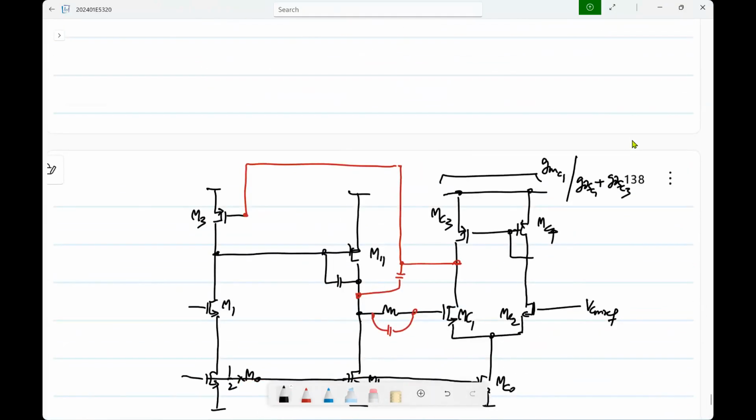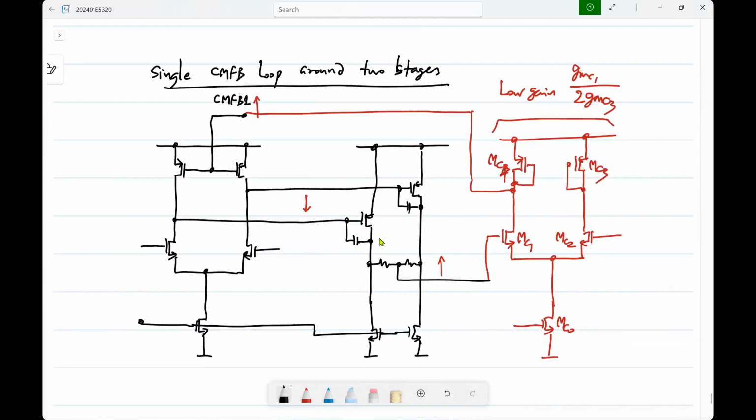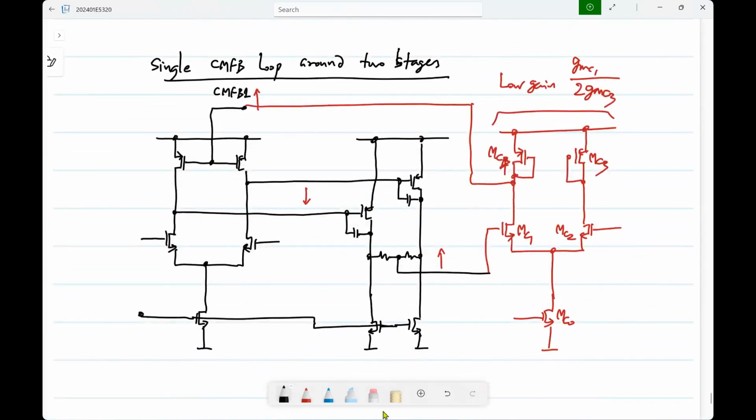No, no, no. I mean, you have only one. You don't need a separate one for the first stage, right? That's the whole idea. Normally, you can use one here and one there, controlling this separately. Now, you have some current here. If the feedback loop is operating correctly, the gate voltages of these two will be stabilized to the correct value, which is VDD minus VSG of these devices at this bias current.